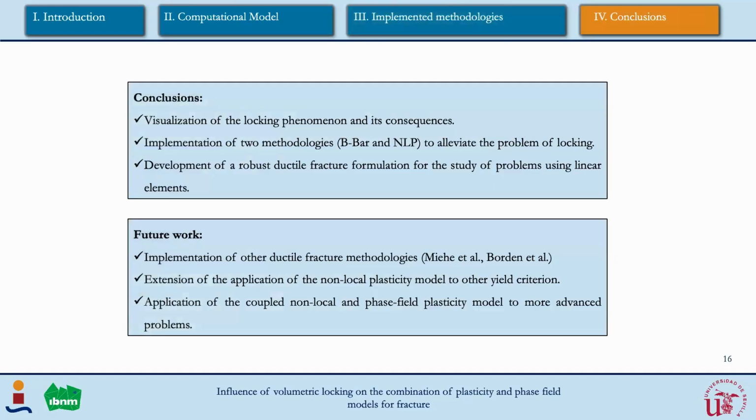And as for the conclusions, we were able to see the problems that can arise from locking phenomena when working with linear elements. We implemented some methodologies, the B-bar method and the non-local plasticity model, in order to alleviate this kind of locking. And also it helps to develop a more robust ductile fracture model in order to study this kind of cases.